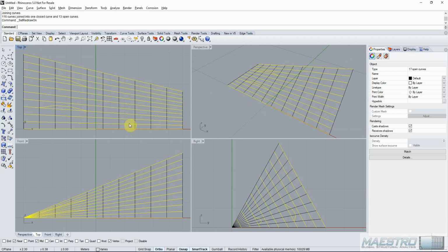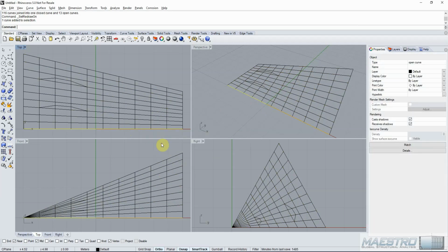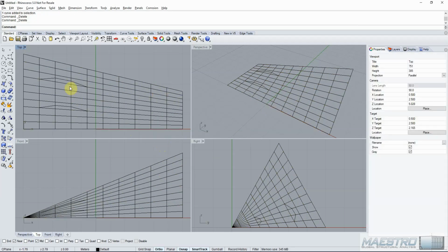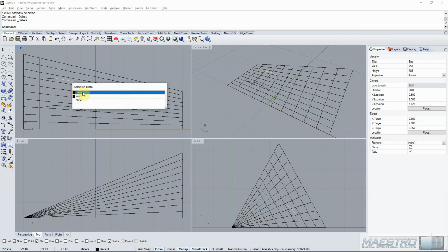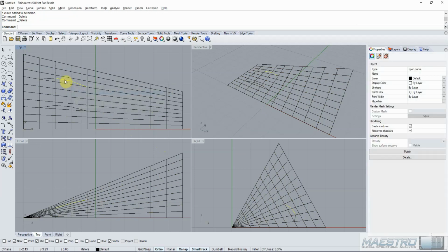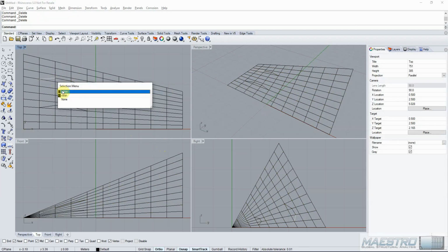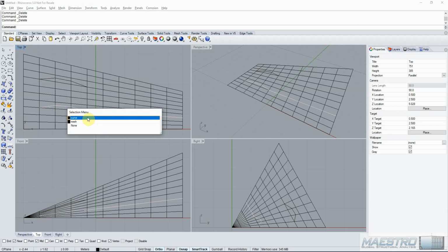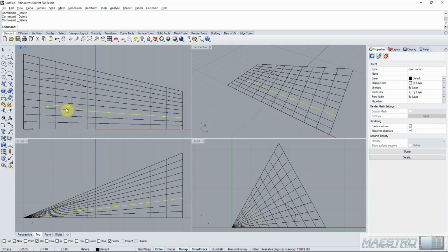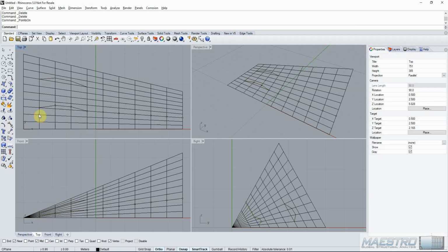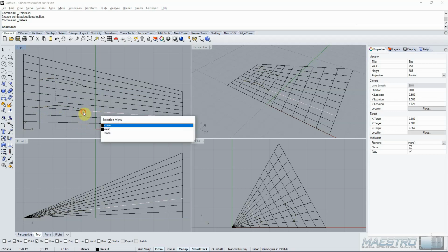In this case, if this was, say, side shell plating and we were extracting the longitudinal stiffeners, we most likely would not want these curves at the edges, since there would be a deck below and above this section, and these additional pieces in here would need to be removed. Now, there's no control over how exactly the script joins the curves, so you have to check each one, and in this particular case, for editing this curve, the user would have to either explode the polyline and deselect the segments they didn't want, or they could turn on the mesh points and delete them. It's really up to the user how they want to go about the editing.